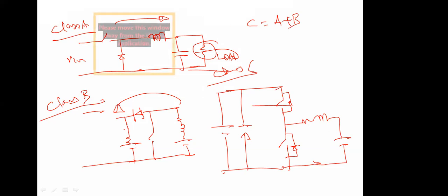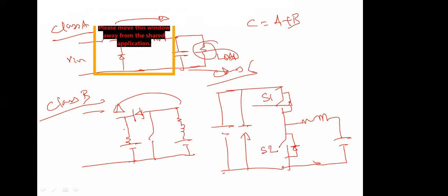And so what it will do, for the class A operation, switch S1 has to be operated, right? For the class B operation, S2 has to be operated. And what will be a 4-quadrant chopper? It will be a combination of C type of chopper against C dash type of chopper. Means this is my own created C dash, right?